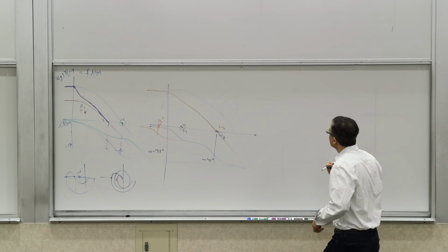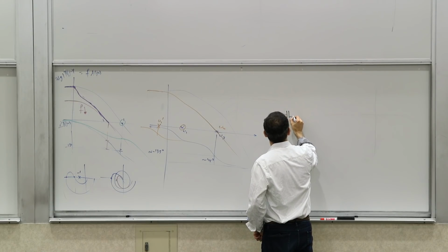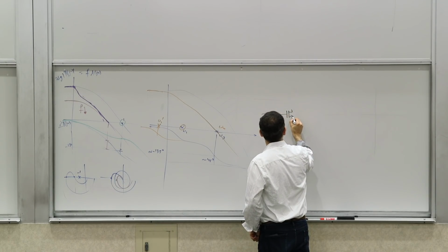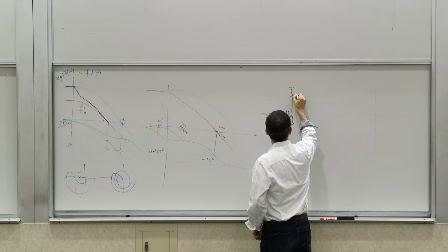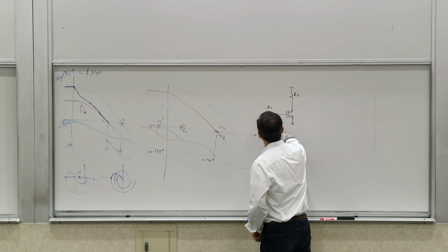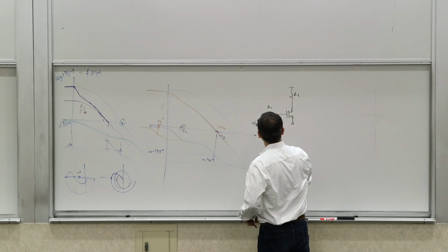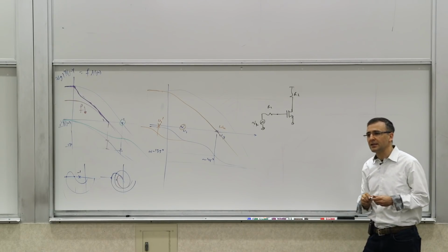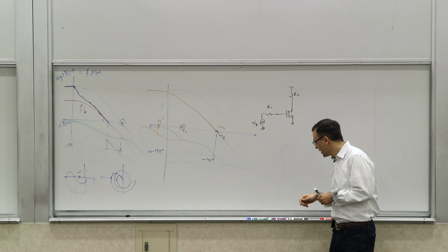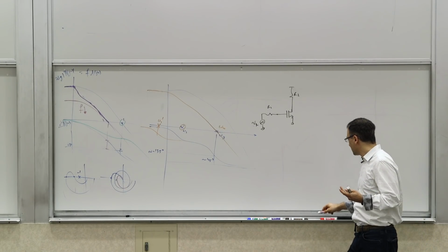So how do we do that? Let's say you had an amplifier with a resistive source and a resistive load, R1 and R2, and you're trying to apply some sort of a VN, and you want to reduce the bandwidth of this thing. If you had something as simple as a common source, what are some of the simple ways of reducing its bandwidth?